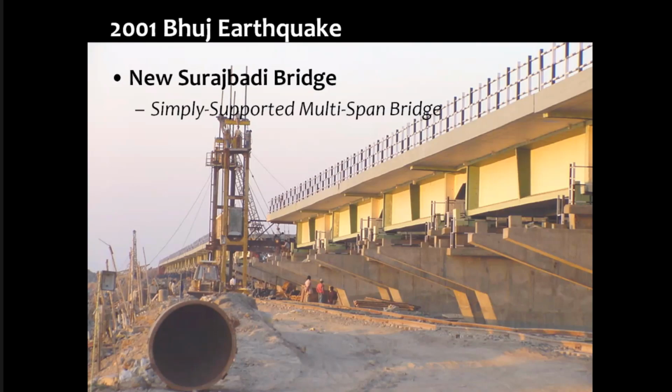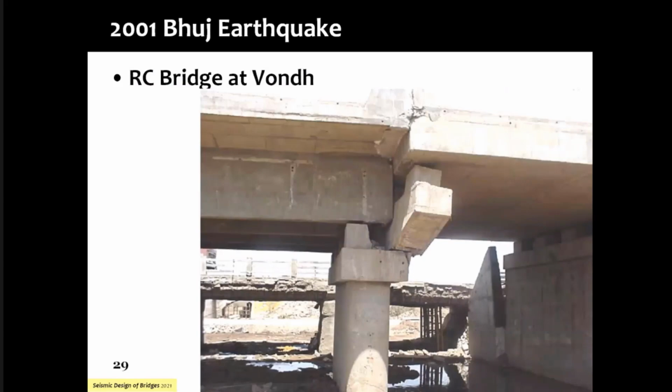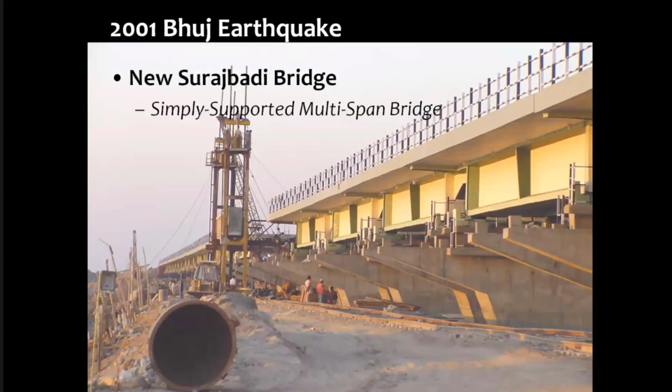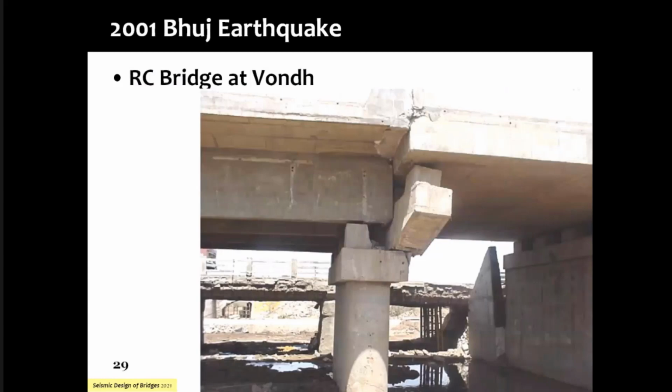In fact, this bridge earlier at the design stage did not have the lateral restrainer, and the peer reviewer had insisted on the lateral restrainer. It was provided, and as a consequence, when the bridge jumped laterally and vertically, the spans did not get dislodged from the pier. That is a very major gain for the transportation system, because the one span that was unfinished, they quickly put that together and they could provide this as the main artery for travel when the parallel adjoining bridge did not function after the earthquake.